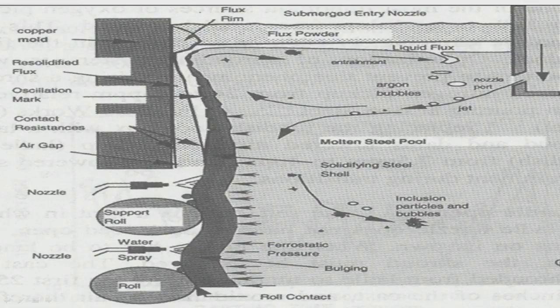So, liquid steel is coming from the Tundish through this nozzle, which we are calling the sub-entry nozzle, SEN. So, this is the port, the nozzle port, through which liquid steel will come inside the mould. So, what is happening? Through this port liquid steel is coming, also we are passing argon. So, there is some argon bubble also coming out in the liquid steel. So, this will take this path and go to the surface, where we have mould flux, or we call it